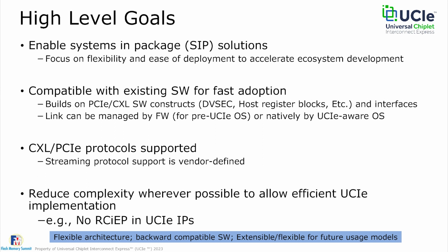Compatibility with existing software for fast adoption. So that's number one. It builds on the PCIe and CXL software constructs, the DVSec, which is the extended capabilities registers which PCIe has defined, and then the link can be managed by firmware, right? So for interoperability, we need to be able to bring up that link. It has to seamlessly come up and work the first time. So using existing facilities is going to help with that effort a lot.